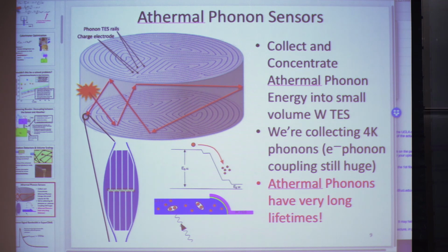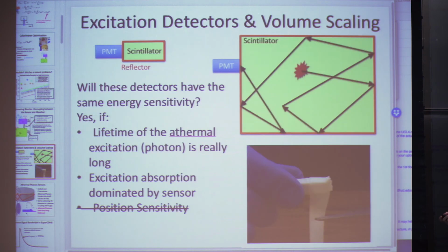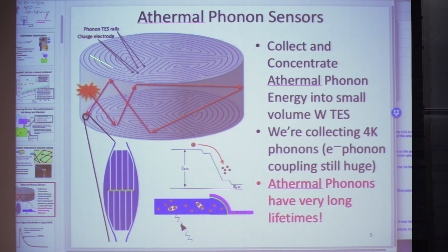Okay? And this is one of those things when you have an experiment and you have a fall time in your system, you never know what it is, right? Is it because of your electronics? You put an extra filter in your electronics. There's all sorts of ways that one could get a fall time in your signal. But here we've matched it to the aluminum coverage, and we see the intrinsic fall time. The fall time we're measuring of our pulses is intrinsically limited. It's the amount of time it takes the phonons to be collected.